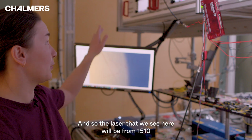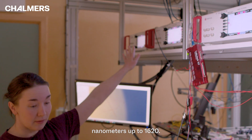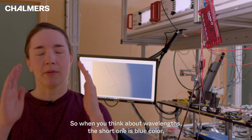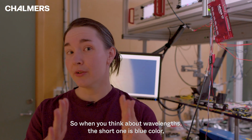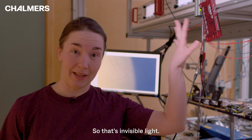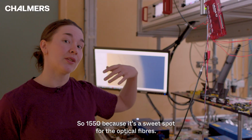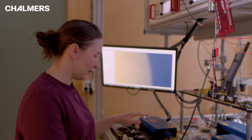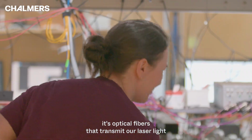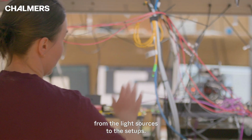And so the laser that we see here goes from 1510 nanometers up to 1620. And this range is out of our vision. So when you think about wavelengths, the short one is blue color, the long one is red. And if it's even longer than that, it becomes invisible. So that's invisible light. And we choose the telecommunication wavelength, 1550, because it's a sweet spot for the optical fibers. These are all these yellow, white, no, they're not cables, they're optical fibers that transmit our laser light from the light sources to the setups.